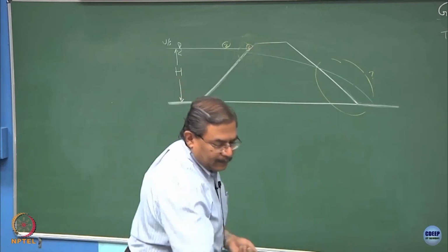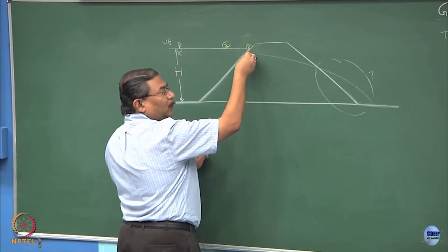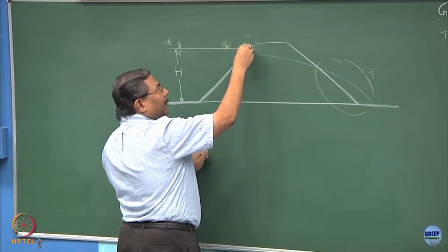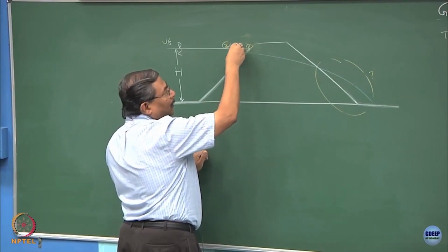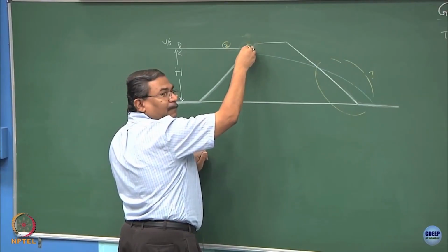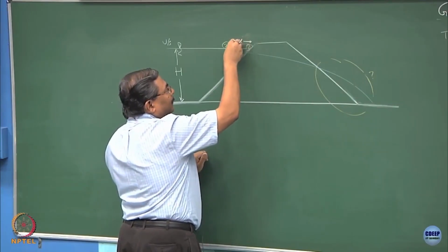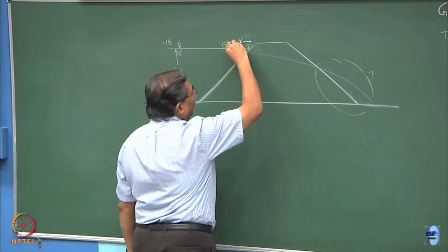As you rightly said, the flow line is going to be perpendicular to the equipotential and not starting from this point where the water is matching with the body of the dam, it will be at a certain distance x. So, the top phreatic line would start like this,